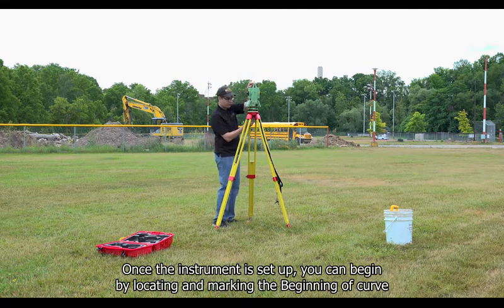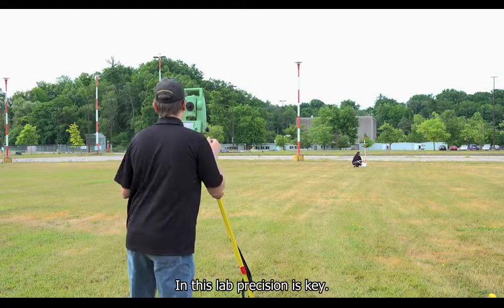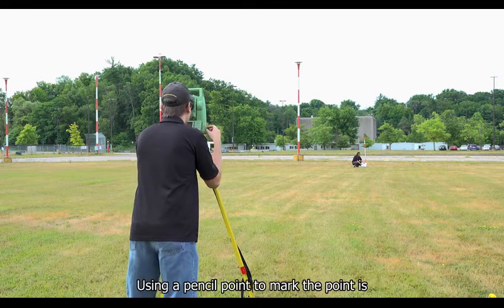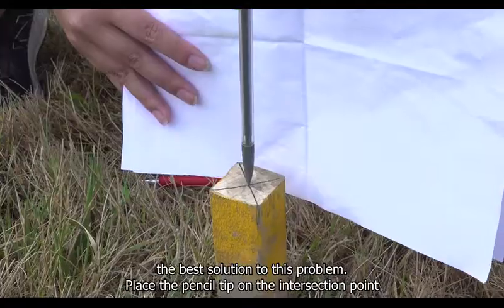Once the instrument is set up, you can begin by locating and marking the beginning of curve. In this lab, precision is key. When taking sights, it is critical to be as accurate as possible. Remember, the errors accumulate. Using a pencil point to mark the point is the best solution to this problem.